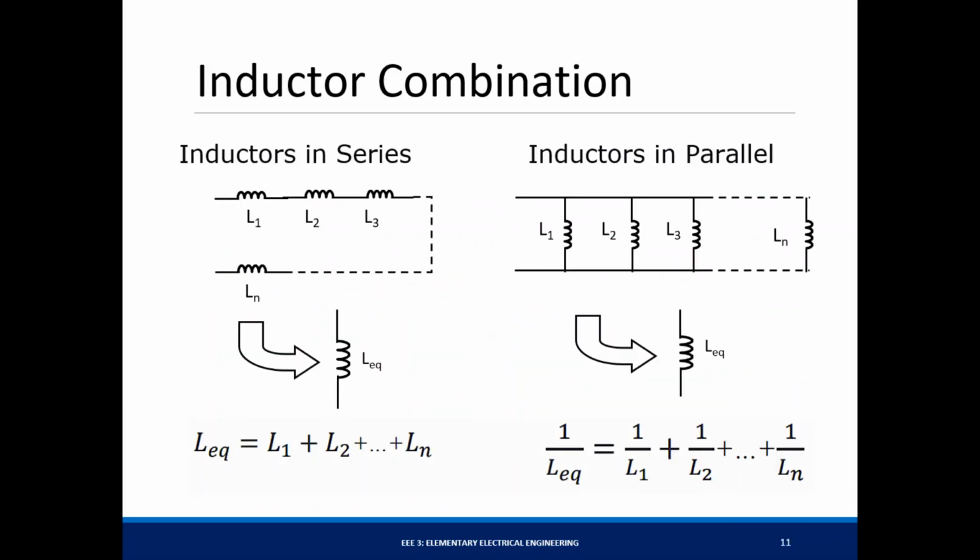Okay, but once we analyze it in the alternating current domain, AC domain, you have to consider these elements and how they react with the change in quantities. So for inductors in series, let's look at the combinations. Of course, we can connect them in series and parallel also. For inductors in series, you just basically add them up. Okay, how did that happen? They have the same current but different voltages. And to get the effective inductance, you can solve it using Kirchhoff's voltage law. We get this expression right here.